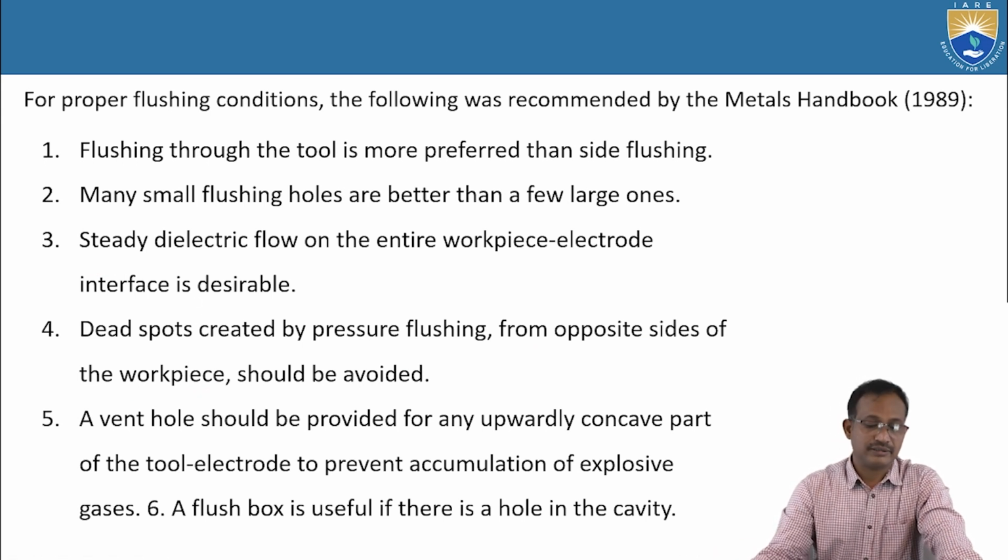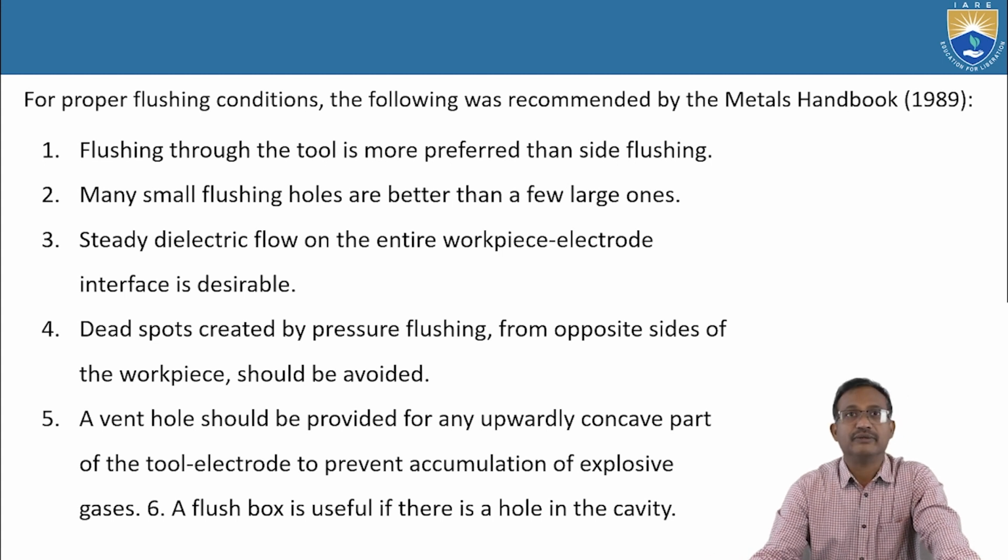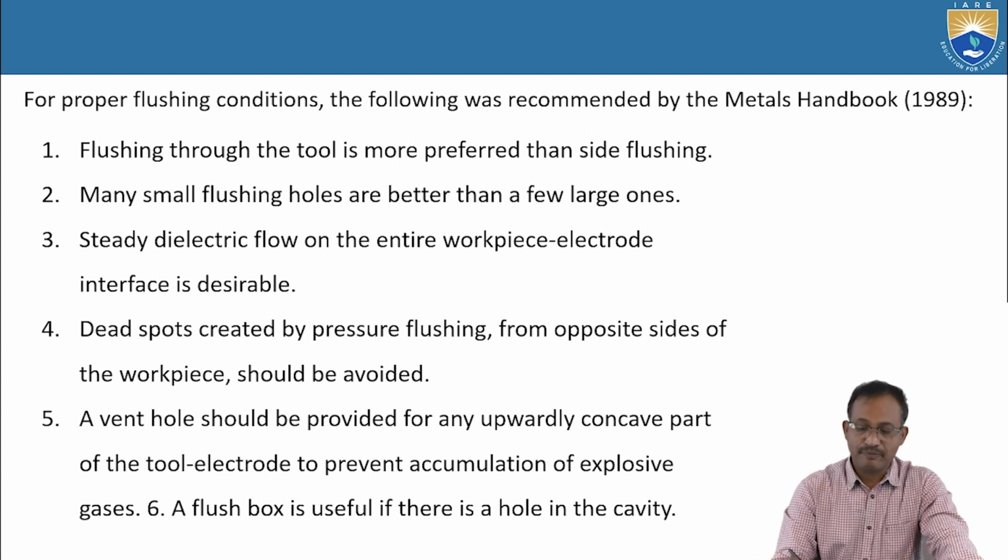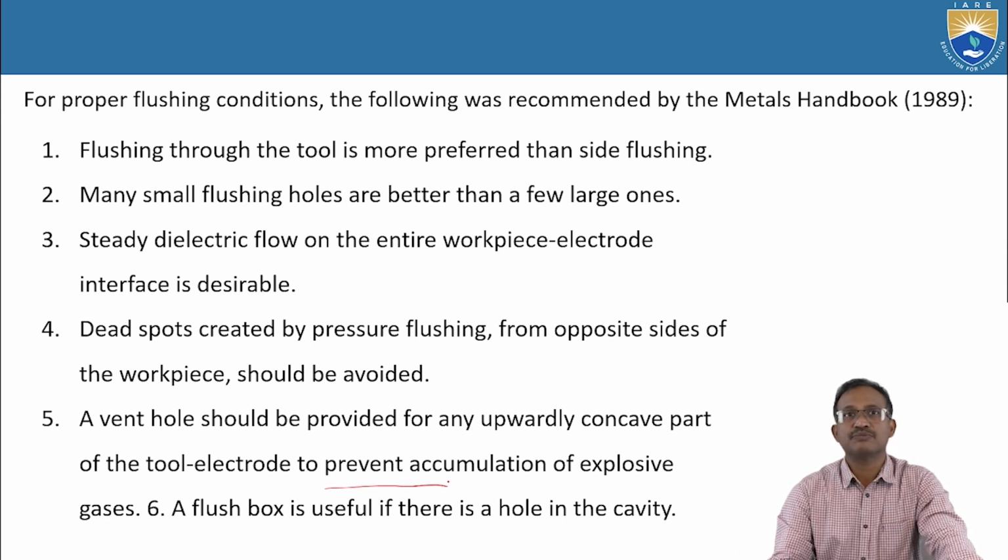Fifth one, a vent hole should be provided for any upwardly concave part of the tool electrode to prevent accumulation of explosive gases.